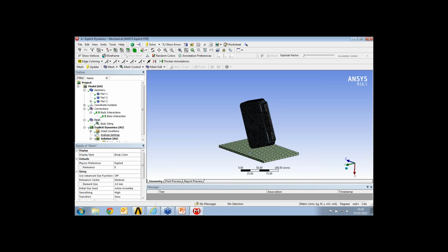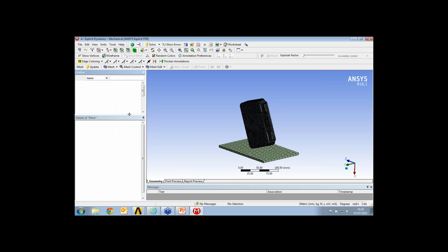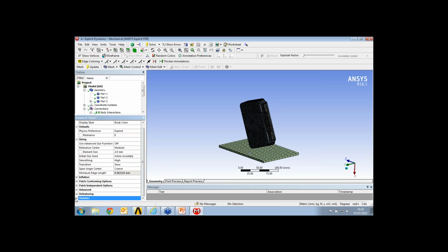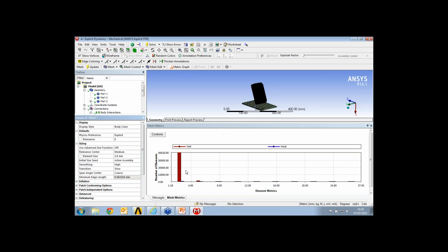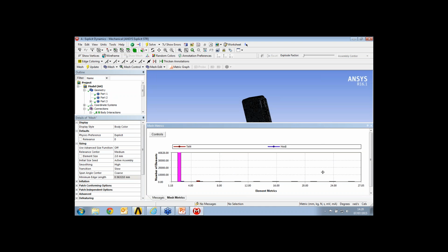All 3 parts are done in parallel, depending on your computer power. That gives us our mesh. Typically we would run through the checks of the mesh and look at the quality checks, look at the aspect ratios to see where the good elements are and where the small elements are that are driving our delta T values.